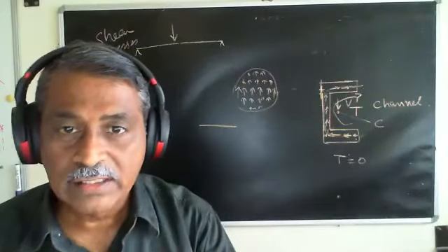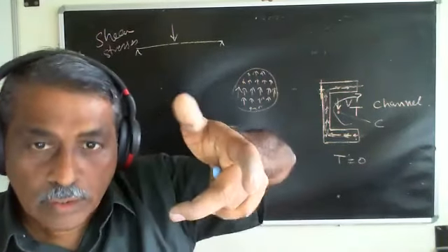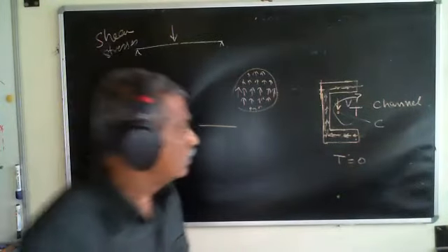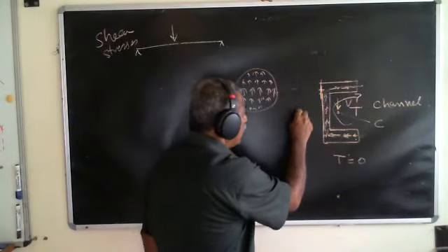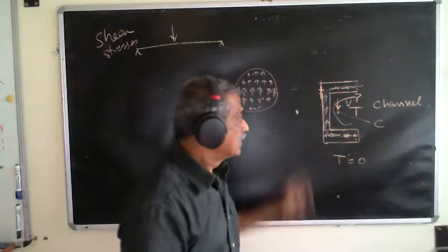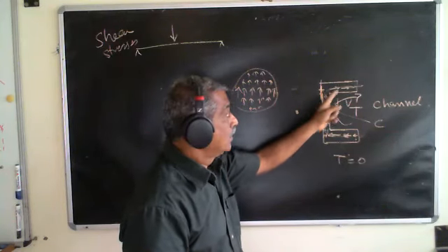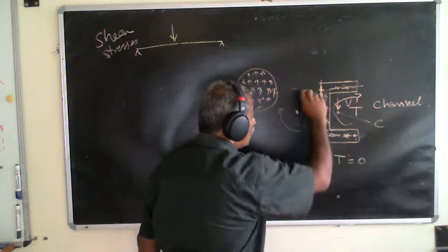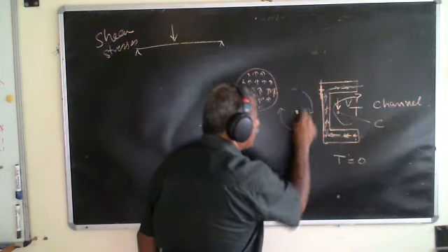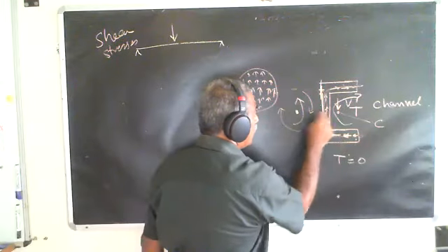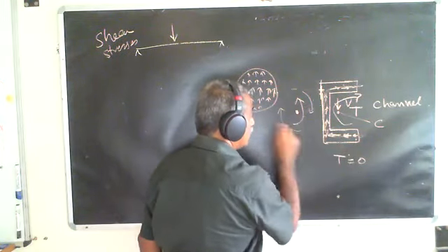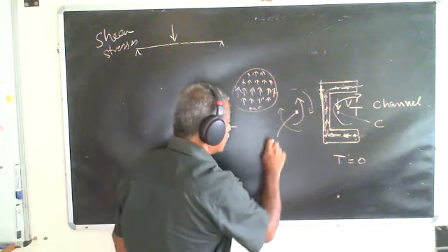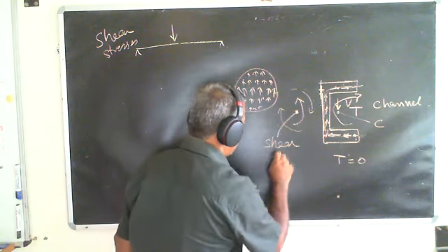And this unbalanced twisting moment is going to twist the beam. If you don't want it, what will I do? I need to find a point such that the moment due to this is causing one direction, and this is causing the opposite direction. I have to match this opposite direction to these and find out what point that is. That point is called the shear center.